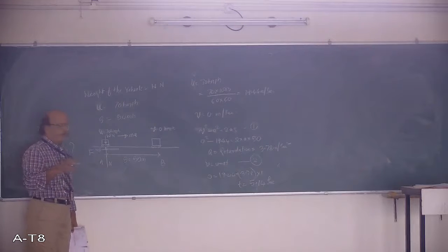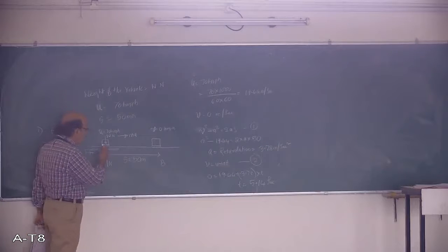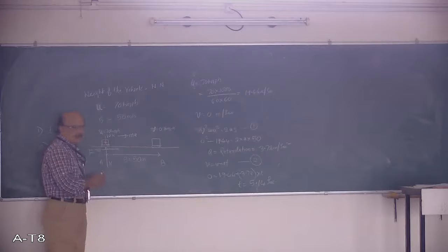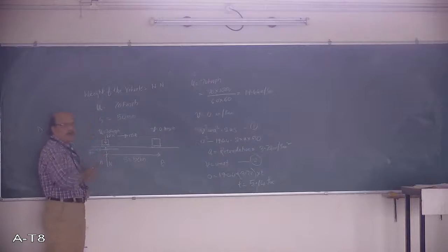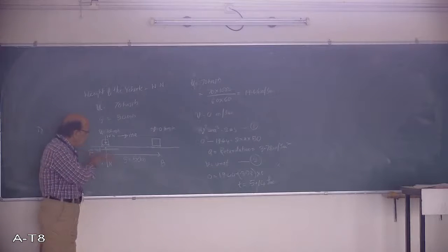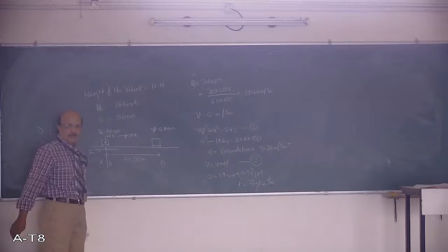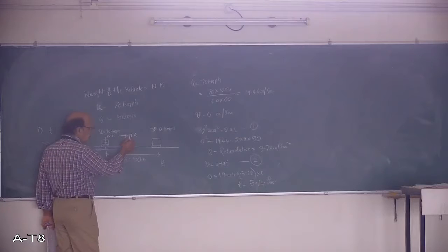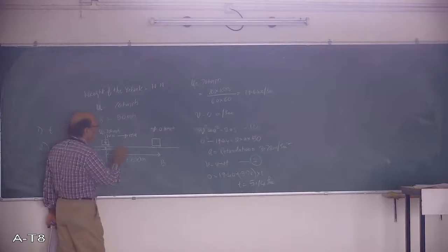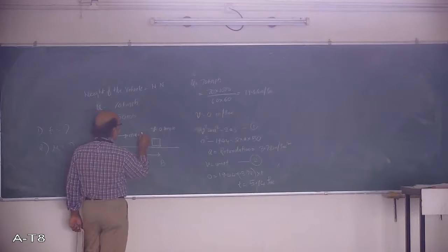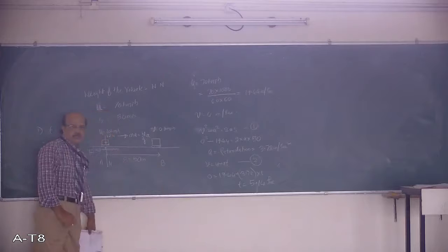The reason is that here the acceleration decreases, so the inertia force will be opposing that. If you are applying brakes, your vehicle will try to stop, but the inertia force is pushing it. That is why the inertia force is acting in this direction. So this will be equal to W by g into a, mass into acceleration.